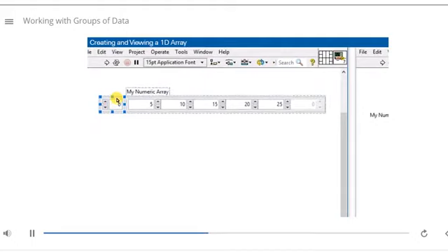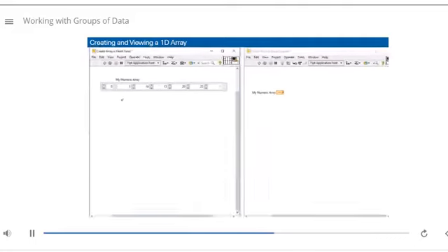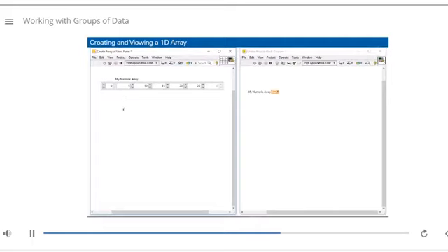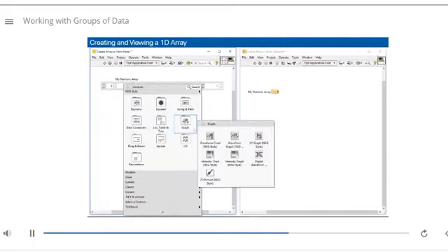This is the array index display, which controls which array element is shown at the leftmost element. Right now, the element at index 0 is shown here. The element at index 1 is shown here. Notice how the array index display affects which elements the array control shows. Now I'll wire this array control to a graph indicator and run the VI.